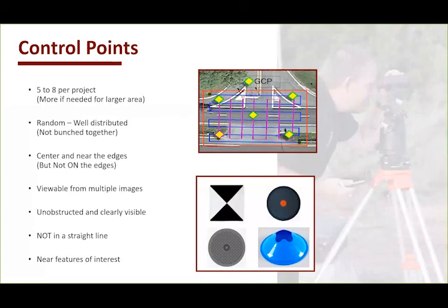And importantly too, sometimes where you're really concerned about the level of accuracy, if you have a point of interest, maybe a gouge mark in the area of impact, or you have a significant change of elevation, place a couple at the high end or the low end. So all those are worked into the solution when it comes to scaling of the point cloud data, and also will assist with the scaling of the XY data when it comes to an orthomosaic TIFF file.